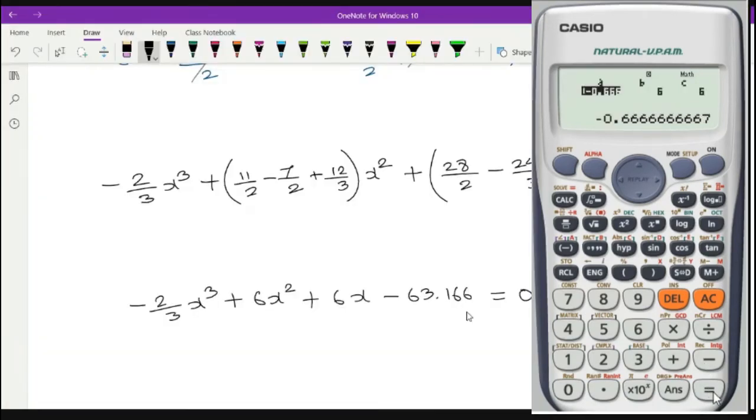So one value we are getting is minus 3. This minus 3 is not applicable because your beam is not a negative beam. Okay, so you can neglect this. Next value is 8.7. If I consider the total length of the beam, it is only 7 meter. So 8.7 is also not applicable. So this also you should not consider.